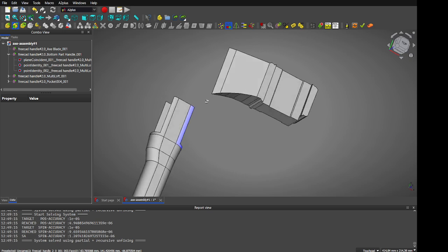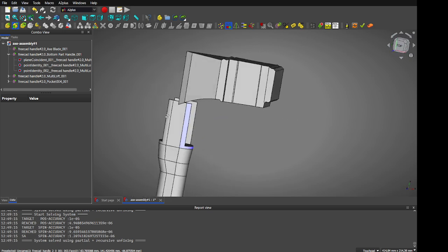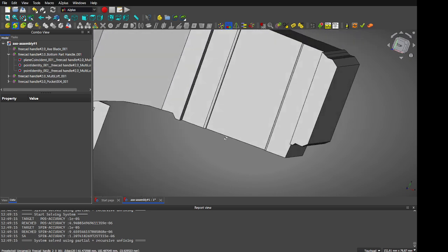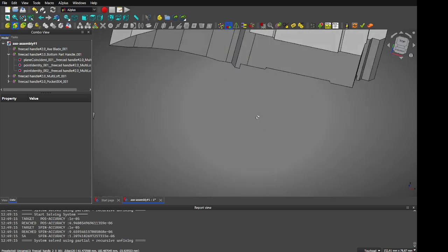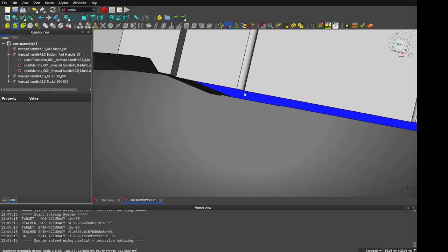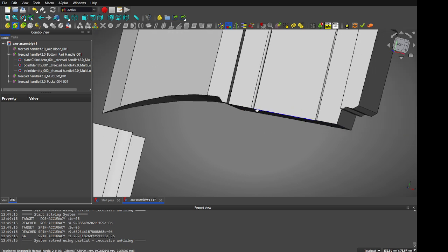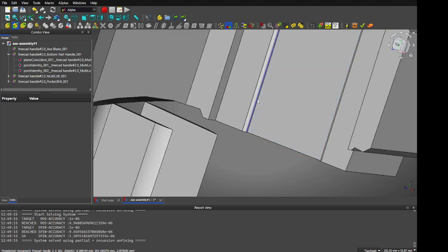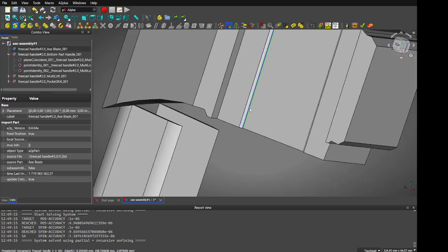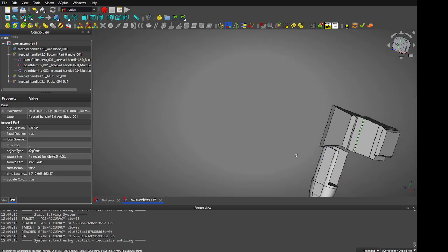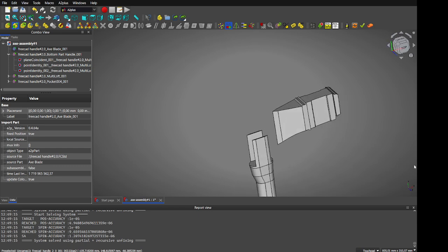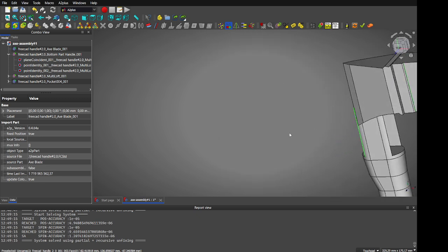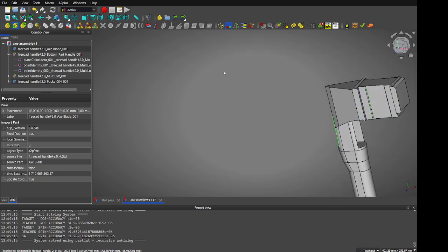And now the last part of the assembly is to attach the blade, which is here really foremost. And you will use for this firstly the line constraint. So click this, hold control, click, and select another line. You have to select it on green.